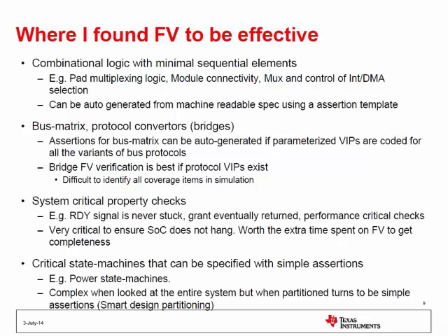And again, the protocol converters, or bridges, what we call converting, because if you are going from APB to AHB, all those kinds of protocol conversions, here again, it's more of a control-specific thing, and usually RTL designers miss very simple things there. It's simple when you find the bug, but to think about it, it's small corner cases which you'll be able to catch here, and it is very useful that you have found them. And another easier way to get into this, as I said, if you're using AMBA or some of these industry standard bus protocols, the VIPs are already available. You don't have to do any work. You just have to plug in those VIPs and you'll be able to get started from day one.